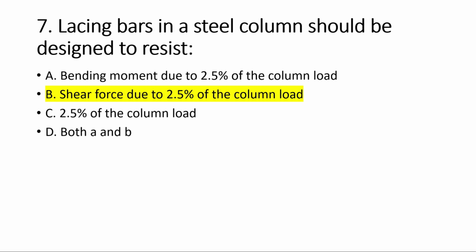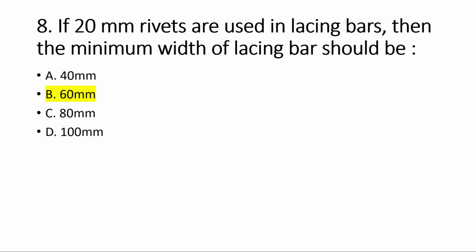And we know the lacing of compression members should be designed to resist a transverse shear force of 2.5% of the column load. So option B is correct. So move on to the next question.